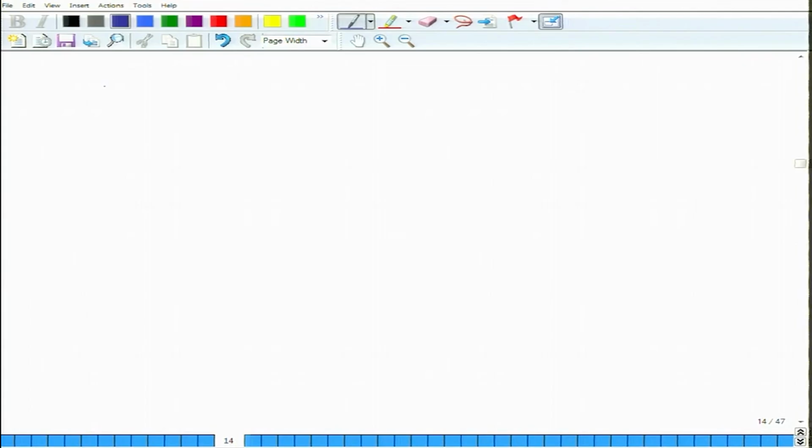First we find epsilon Fu. This is the solution, because to find V min and V crit we have to find the breaking strain in the fiber, and corresponding to that breaking strain, the stress in the matrix. So, first we compute the breaking strain of the fiber.